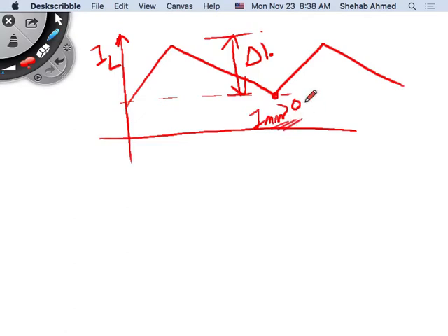We were designing and selecting an inductor starting from there, isolating the discontinuous mode from the continuous mode. But we also said that there's nothing wrong with operating in discontinuous mode. Sometimes you have no load across the power supply, because this is average current. Depending on whether you're looking at the buck, boost or buck-boost converter, this average current is either the input average current or the load average current. So to have input or load average current, you have a load in the circuit, right?